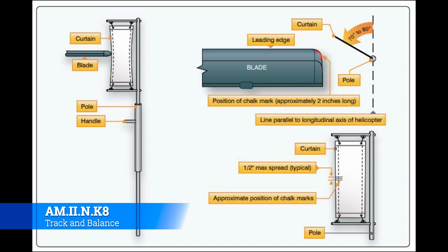And then you go back to your PC links, which is a lot like a turnbuckle, and you make so many flats, we would count flats in the Army. So you would break torque on the PC link, run the jam nut up, and then turn the PC link so many flats, and then run it back down, retorque it, re-safety everything, and then run the helicopter again. We never used the flag and pole method, but if you were, it would make another mark, and you would know if you made the right corrections or not.